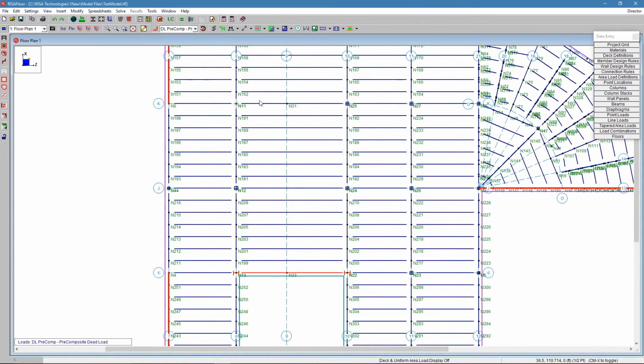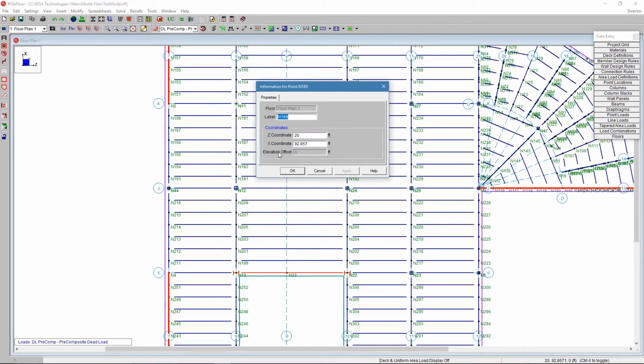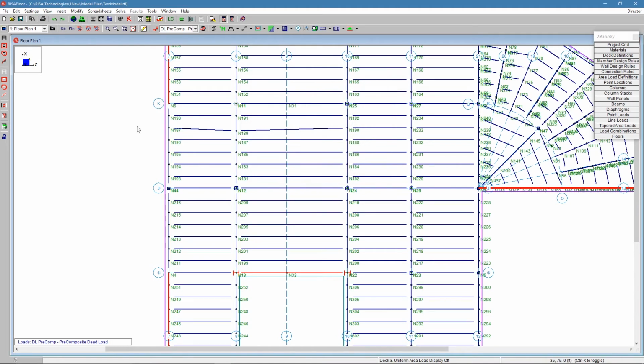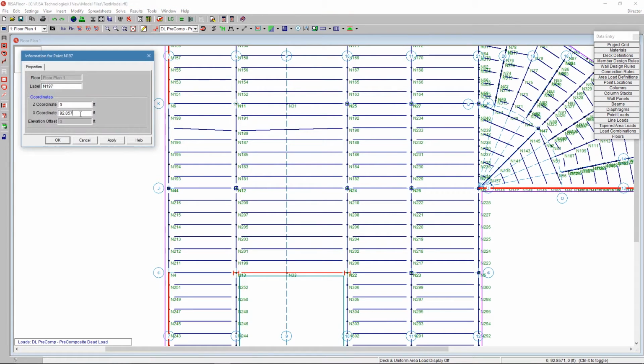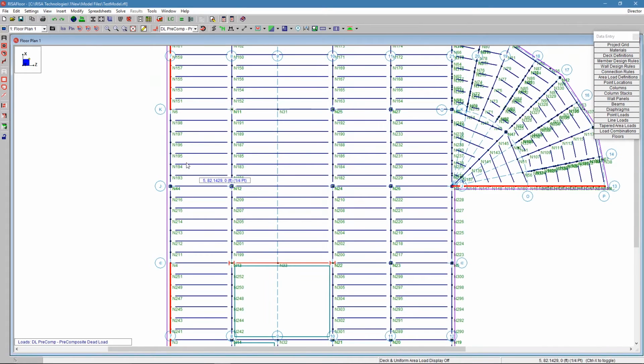Instead of using our new move tool, which is a great tool, in order to just scoot this beam up or down, it's so easy to just double click on it and say, actually I meant it to be at 92 feet, not 91, and change. So I'll drop that to 92, and the rest of these will go to 92. It's going to see this is a shared node, so it's dragging along the width, things like that. You can go across the board, or you could use the move tool, and we'll do that shortly. So let me scoot that back. That's for beams and for nodes, an easy way to manipulate using the double click dialog.